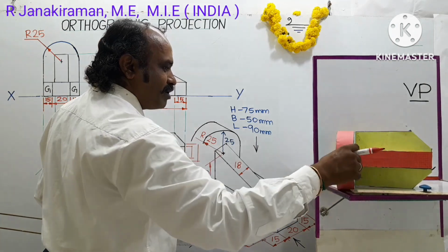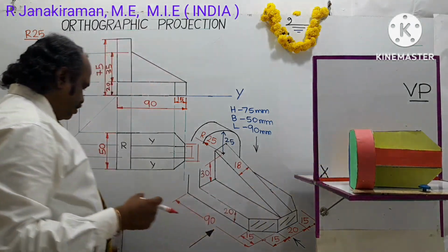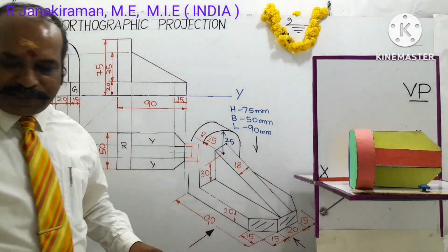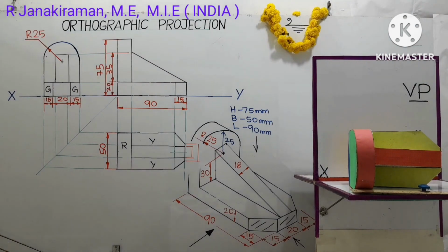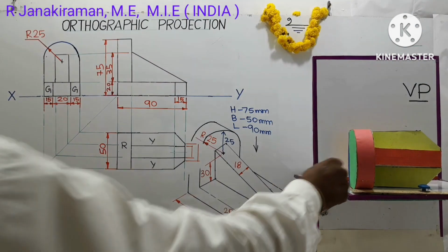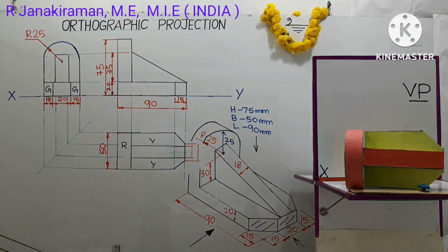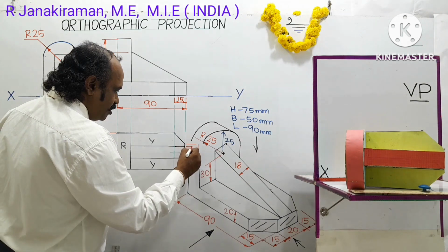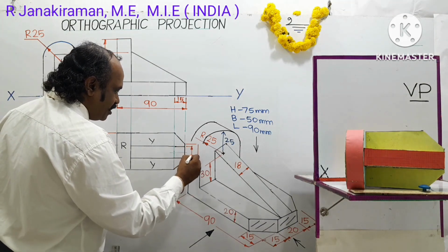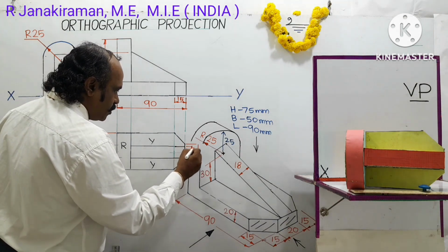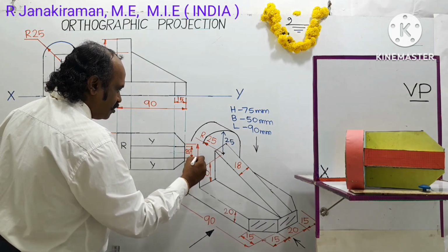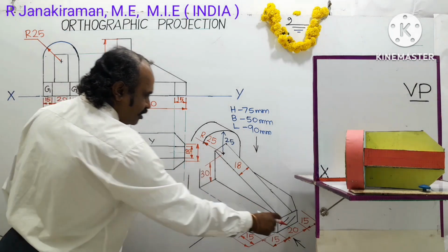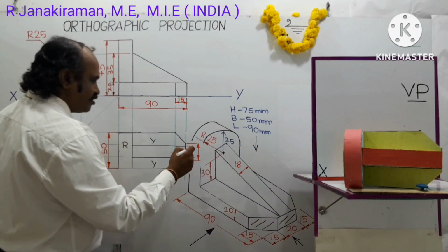In the top view, the observer goes to the top of the object. The portion visible to the observer, I explained previously. So this distance is the triangular part thickness, 18 mm, plus this gold color part thickness, breadthwise distance 20.